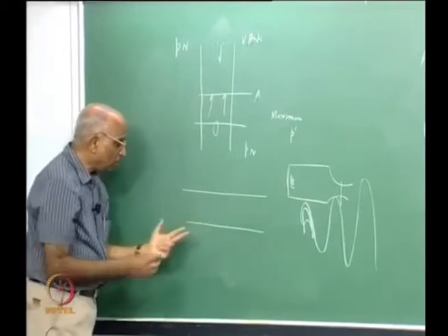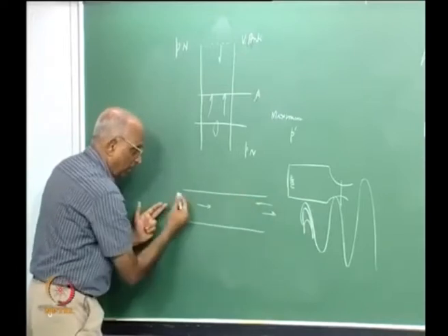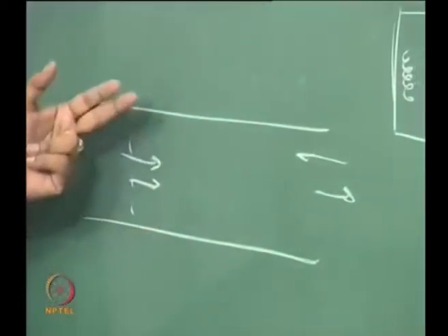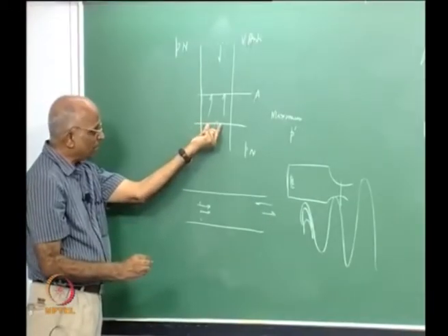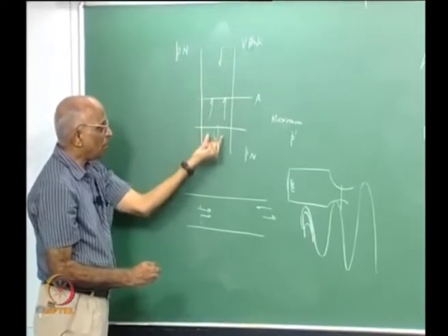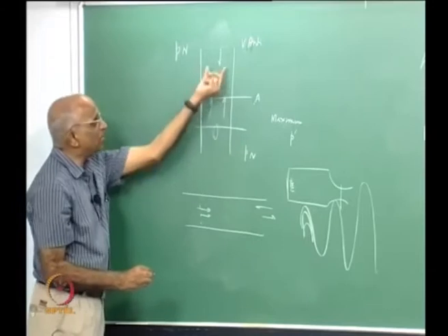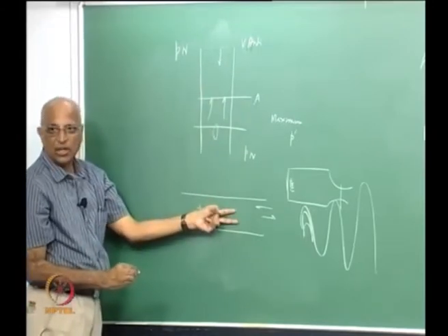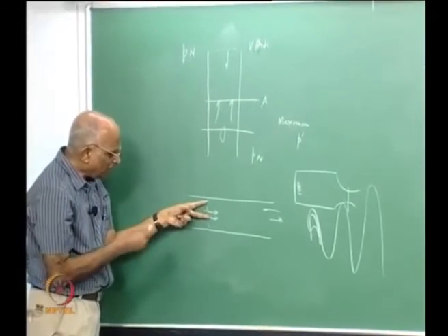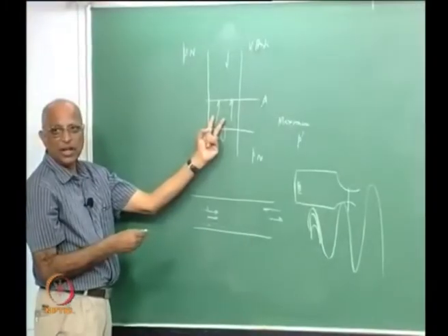If I put a horizontal tube, well, my mass generation is large, therefore some gas goes up, I have the oscillations coming like this, and when I put it here I still get some sound here. But normally the sound in this case was much higher, the reason being I am able to get the convective motion to give me a stronger wave interaction, whereas in this case the velocities are much lower, because here I have the buoyancy effects which help me, in which case it does not help me here. Here I will get mixed modes. If you had really looked at the sound, I would have got something like radial modes and other modes coming here, whereas here it is purely axial.